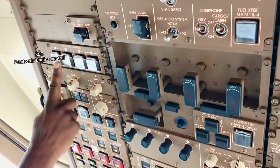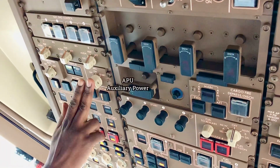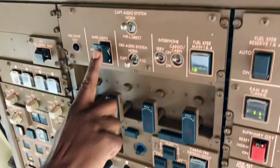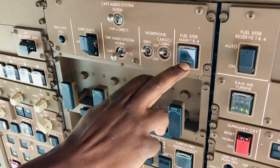Switch, EEC control, navigation systems, they're in the normal position. APU hasn't started yet, standby power is in auto. Electricals, these are the lights I expect to see there. And come up here, emergency lights armed. Audio system, fuel transfer, that's correct.